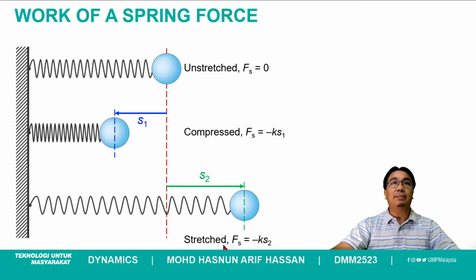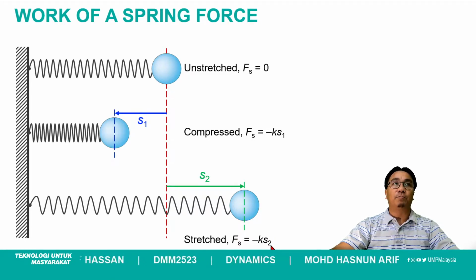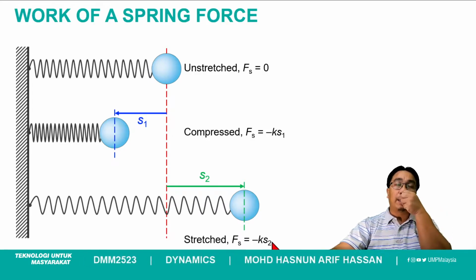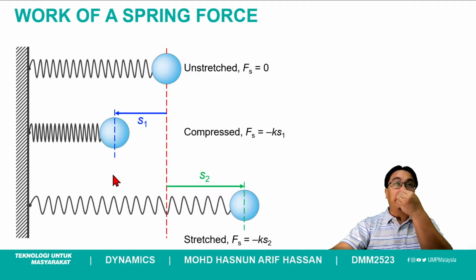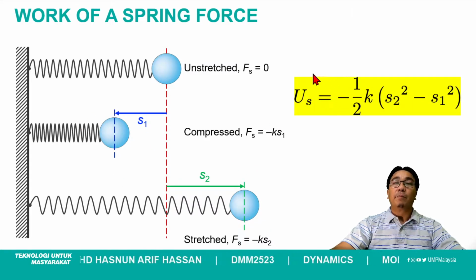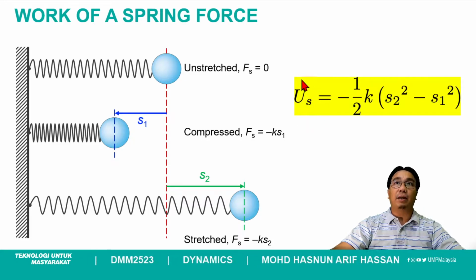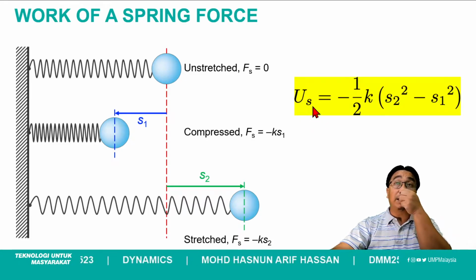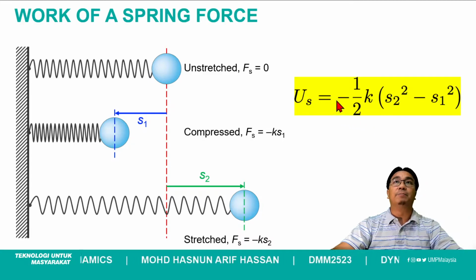So in the case of stretch, the spring force is then minus K times S2. Okay? Many students make mistakes. Okay, before I go there, the work done by the spring, how to calculate work done by a spring, it is given by this formula.